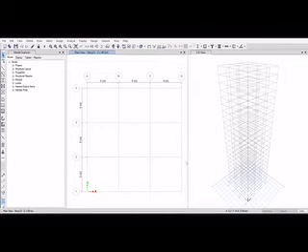Click on OK again. And select the beam cross section defined and click on add copy of property. Change the property name to B550 cross 350. Don't change the material type, keep M40. Change the section dimensions to 550 cross 350.